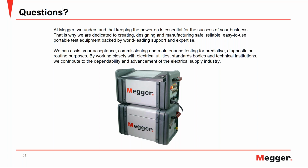I've seen cases where there is an electrostatic shield between the high voltage winding and low voltage winding, and because of that there is a very small flow of leakage current between high to low voltage winding when you perform CHL. And then you look at the power factor value, and it looks very, very good, like 0.005 or something, and you think your insulation is good, which is not the case, because there is very little current flowing through.